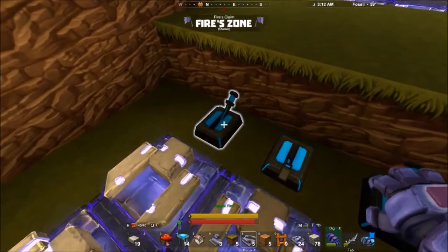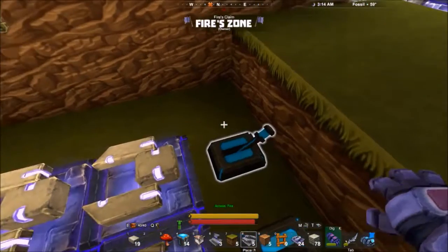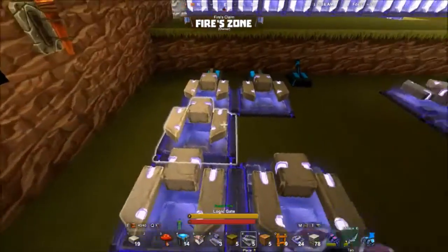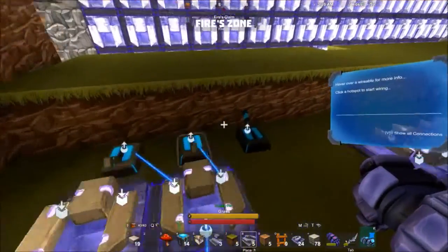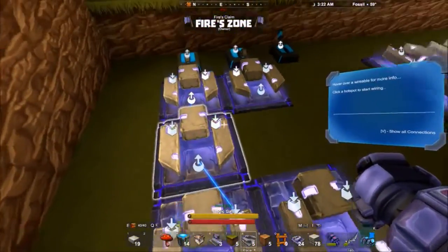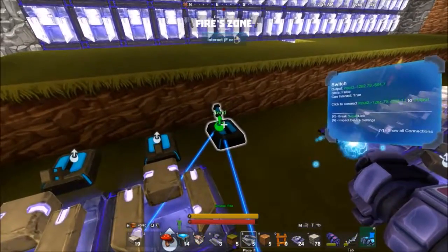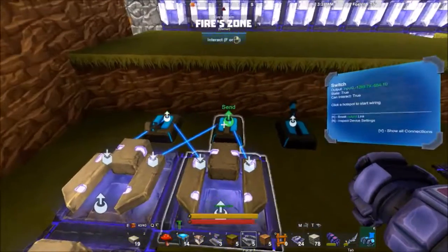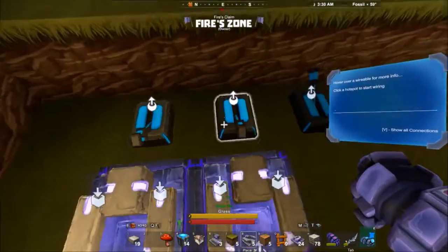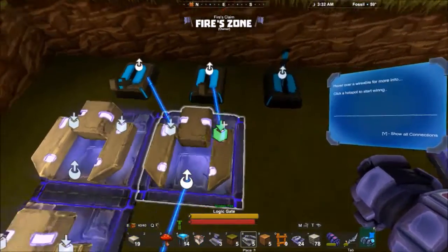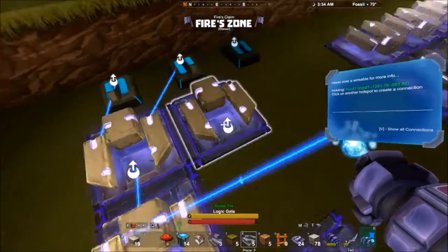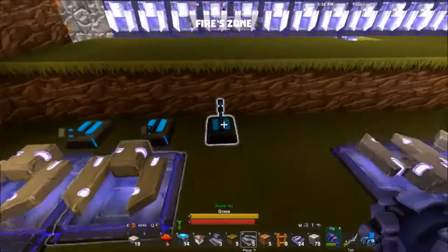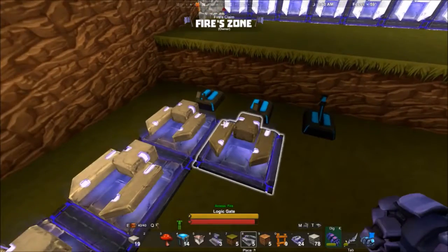So yeah, if I have a 1 and a 1, it's going to be 2. The other situation is that you have to take into account the carry. This gate right here is going to be 1 if one of these is 1 and the other one is 0. So I have a 1 and a 0, this is going to be 1. And if you have a 1 here plus a 1 from the carry, you're going to get a carry.